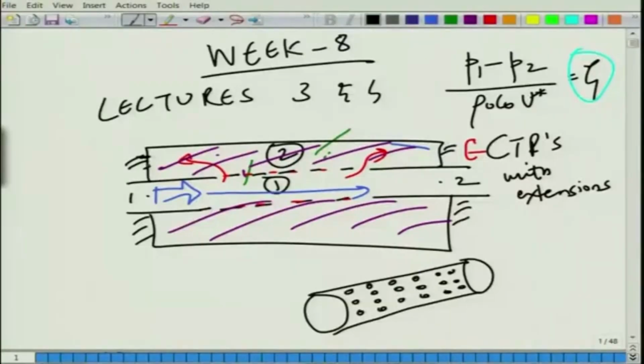Here at this interface, the normal velocity of the fluid is equal to the time rate of displacement normal to the plane of the plate, and your plate itself is governed by maybe your Kirchhoff equations. It could be a thin or thick circular plate with a concentric hole at the middle, and then your other condition is a pressure condition which acts like a loading condition, and this will radiate noise outside in the far field, and similarly here.